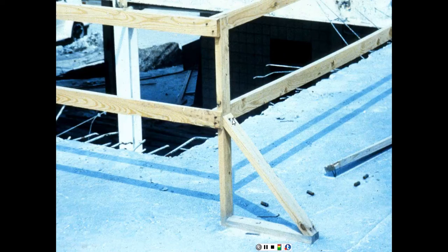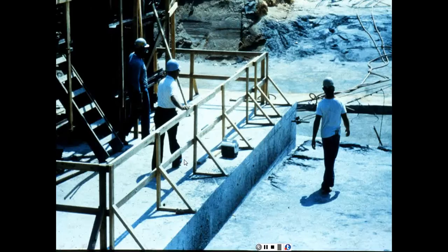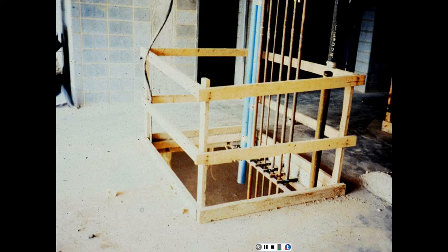This one is well reinforced, so this is a good practice. And since we have installed it away from the opening, then in this case we don't need the toe board, because nothing's going to fall directly on the people standing under this opening. So this is fine. This is fine as well.